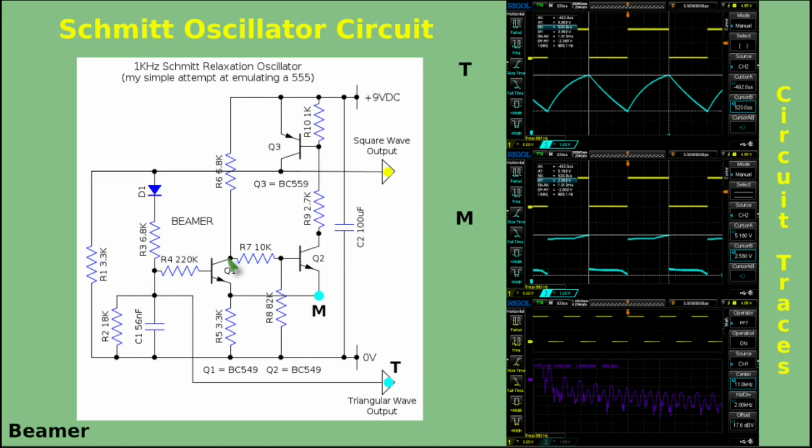And when they switch over, they operate the trigger conditions in such a way as to encourage the switching. But the analog input has to be exceeding that of the trigger level. If the analog level is lower than the trigger levels, then these two transistors will never change states. The function of the input that I've just described about encouraging a trigger level is called hysteresis. And hysteresis is what a Schmitt trigger is all about.